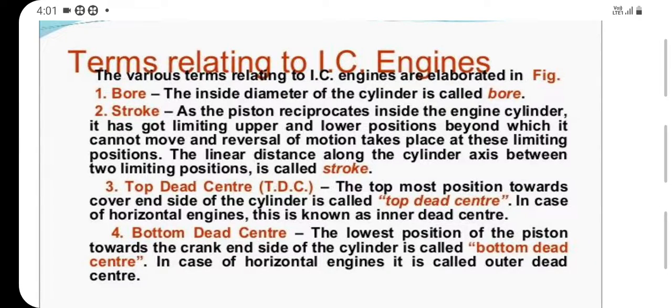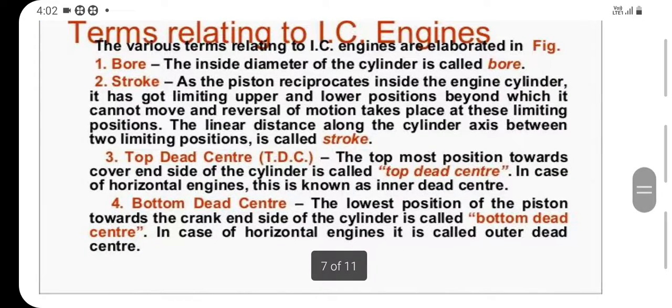Stroke: the piston moves from TDC to BDC or BDC to TDC, vice versa. The linear distance of movement of the piston from TDC to BDC is called a stroke. TDC is the topmost position towards the cover end side of the cylinder, called top dead center. In case of a horizontal engine, this is known as the inner dead center.